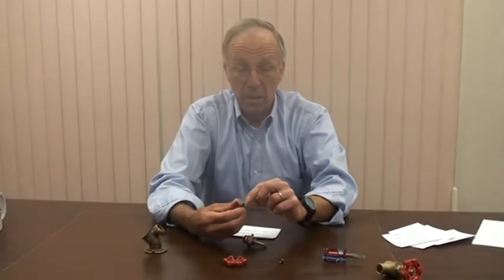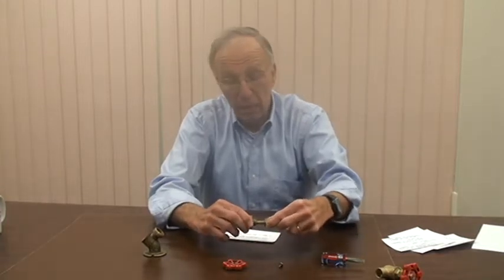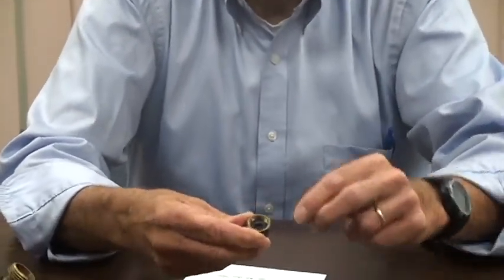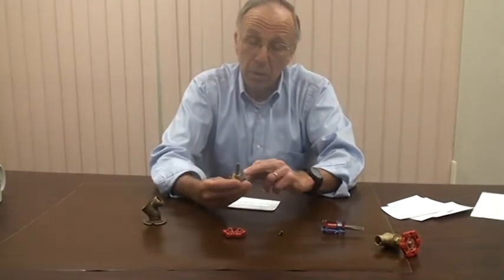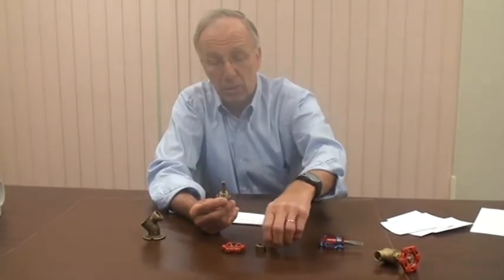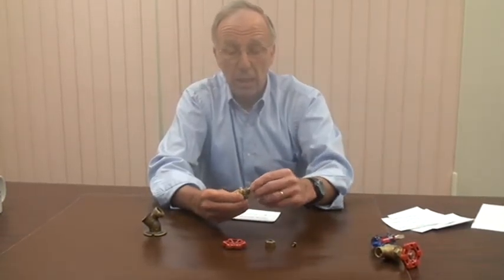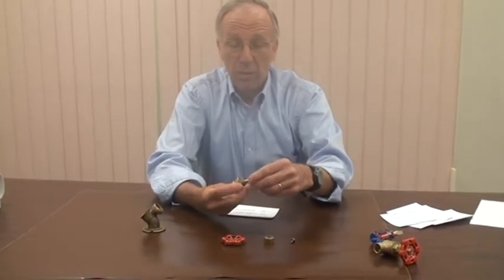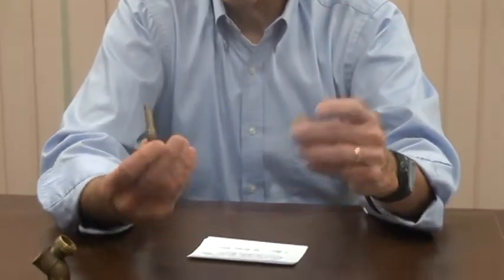And so this threaded piece clamps down in this region, and there's a fiber washer inside which may or may not be entirely visible that seals the fitting onto this piece so it won't leak along the stem. So there's really two pieces there. If I take out the fiber washer, I may damage it, and therefore I'm not going to do that. That allows me now to unscrew the stem this way and get two pieces.